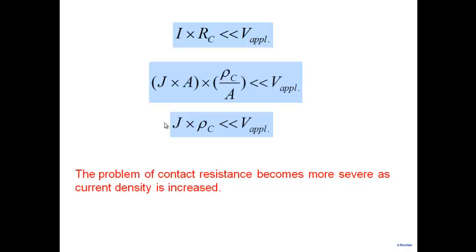If you have a smaller transistor, what happens to current density? It goes high. But what is the advantage of a smaller transistor? You use smaller silicon area, so it becomes cheaper. That's the first thing that happens here. The smaller the device, the smaller the silicon area that you use, and the cheaper it gets here.